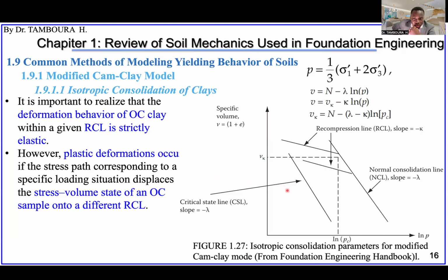Simple. In that case, if we go above this point, then we will enter plastic deformation. It will not be elastic anymore. This zone will be plastic. You understand the difference between elastic and plastic? Elastic means you can still recover the deformation. But if you enter here, you will not recover all the deformation you have caused.